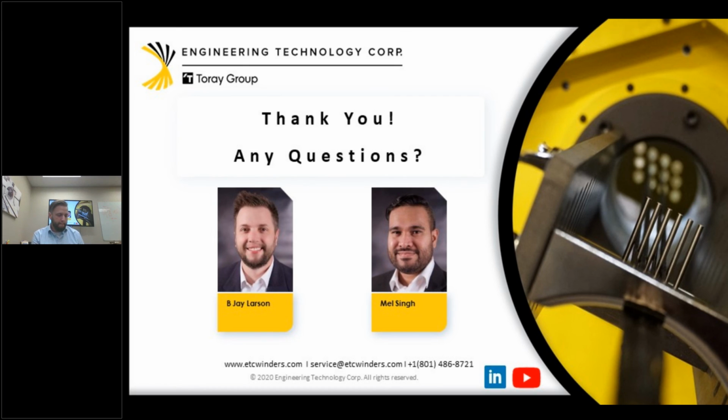Next question. When would I need to use a YAW or yaw axis? Kind of as I mentioned in the presentation, yaws are only used by our customers making very complicated parts. The fiber will come in, and if you're going over a large dome and want to keep that fiber very flat going over that dome so you can control your buildup and your consolidation, you would use a yaw axis in that application. It does complicate the fiber delivery quite a bit, but they are available.